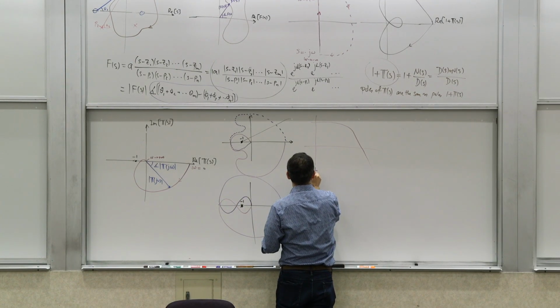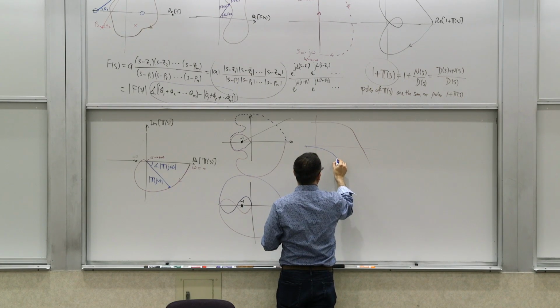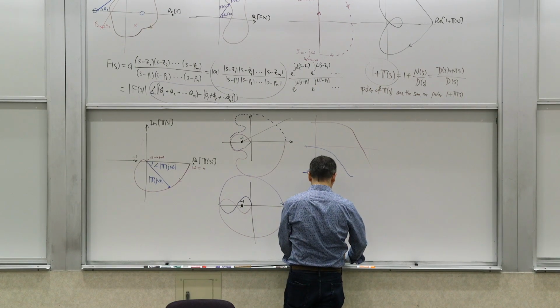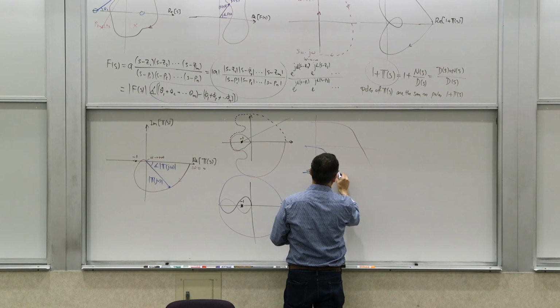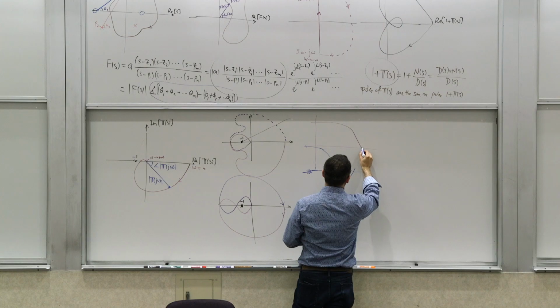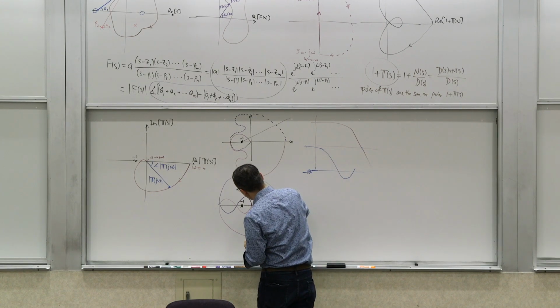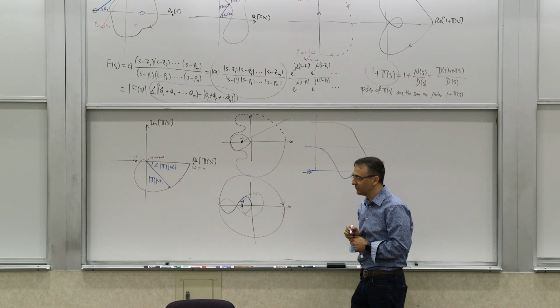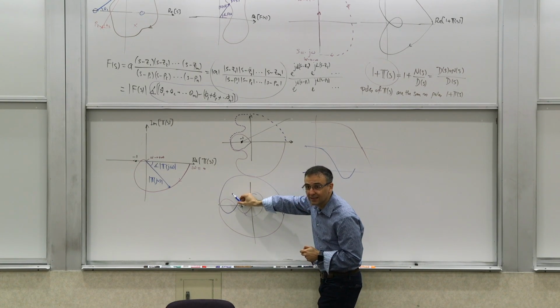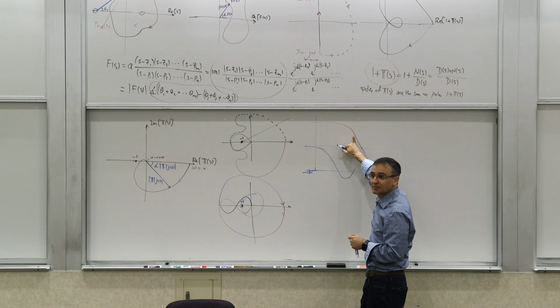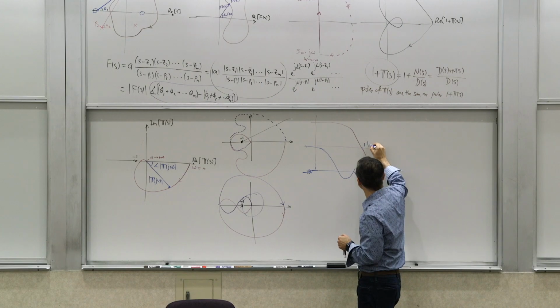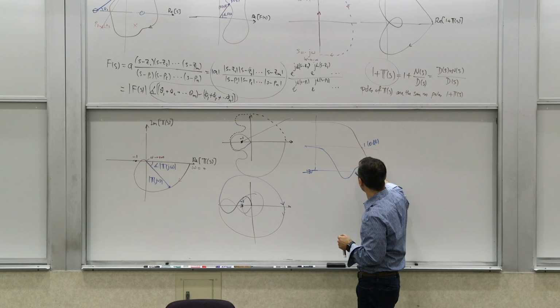let's say this is negative 180. The phase is going down below 180, but it's coming back up before you hit unity, because this is the unity circle. So the phase goes beyond 180 when the gain is greater than 1. Let's say this is 1 or 0 dB. And then it goes back up.